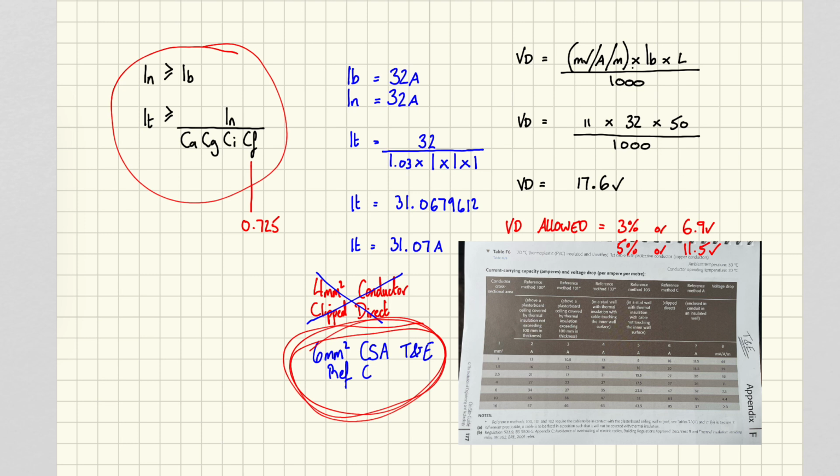less than 30 degrees. If your cables are for a lighting circuit and they're going to be in a loft where we know that the temperatures are higher, it might be worth leaving them at the 30, and then that would be a 1. If you think it's going to be in a greenhouse or something like that, or in lofts it is hotter through the summer, you might want to add a derating value, again taken from the on-site guide or from BS7671, that will derate the cables further. But that is a basic introduction to how we calculate the correct conductor size for our cables.